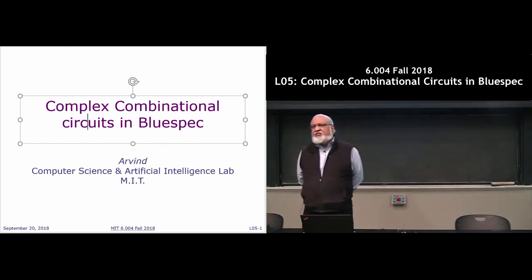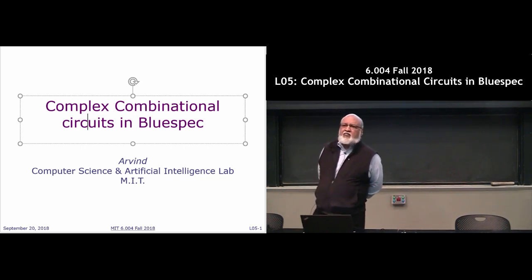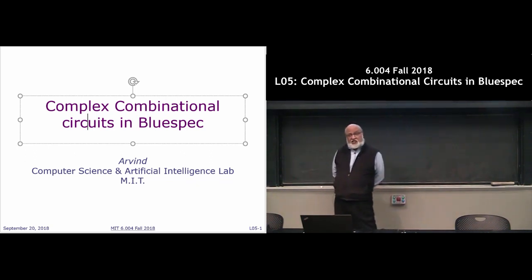But does the circuit have any kind of differentiation? Like, is there anywhere in the circuit where it's defined that this thing must receive a bool and this thing must receive a bit? So it depends at what level you are asking this question. At the Bluespec level, absolutely. If it's expecting a bool and you give it 1 or 0, it's going to fail.